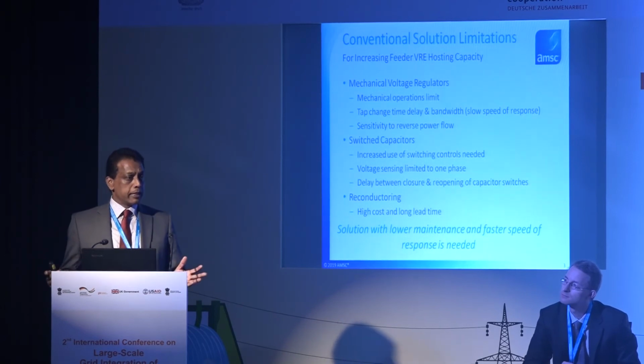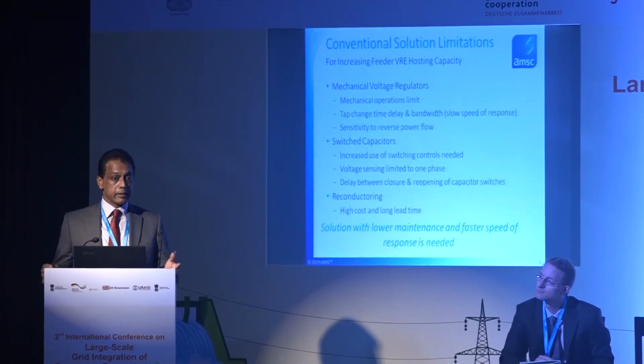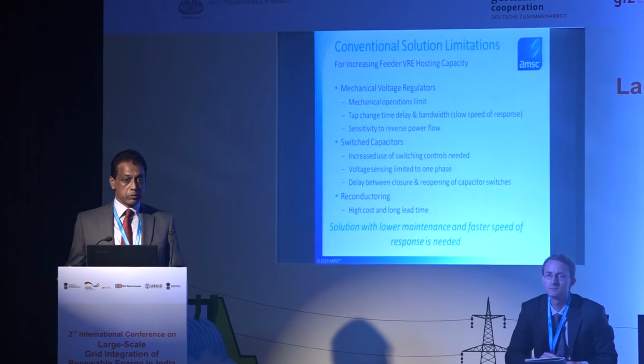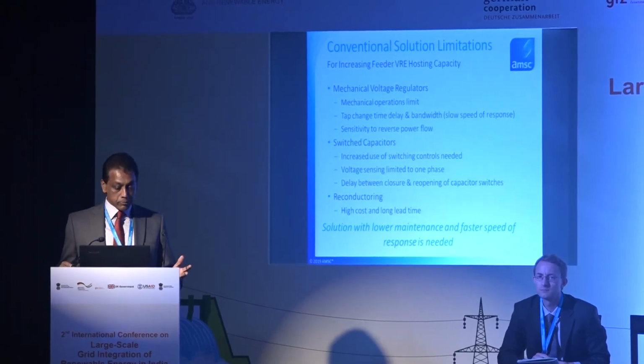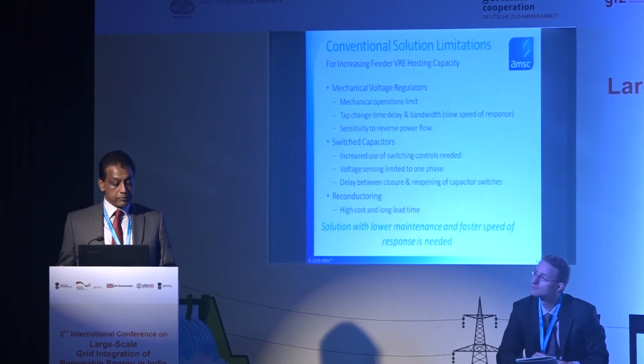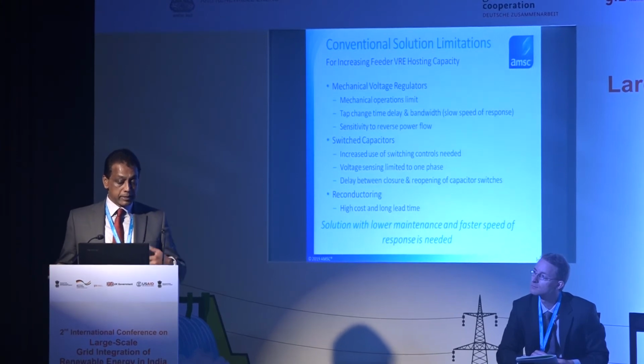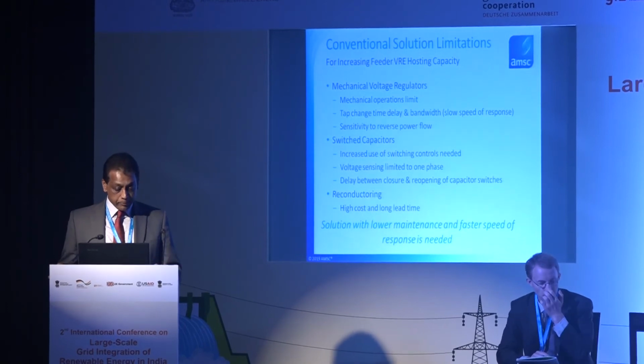Today, your distribution system includes traditional devices such as mechanical voltage regulators that handle voltage changes. As I said, power flow has been designed for going from the substation to the load side. The voltage regulators monitor the voltage change at their location, and if the voltage band is way out, then it actually taps and brings the voltage on the load side higher.